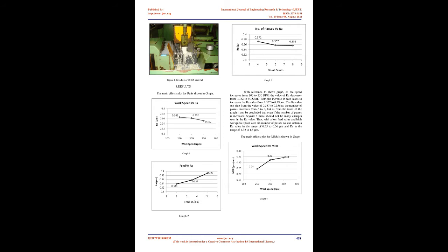According to the experimental studies performed, the grinding compressive residual stress can improve the fatigue life and stop the initiation of crack propagation of the workpiece, whereas tensile residual stress has a negative effect on the fatigue life of the workpiece.